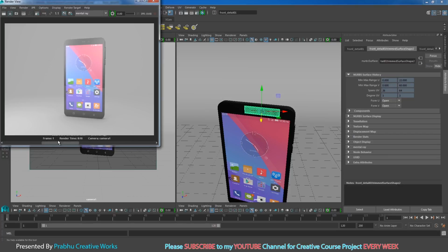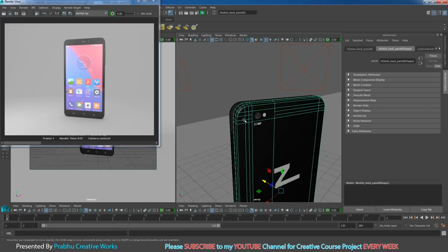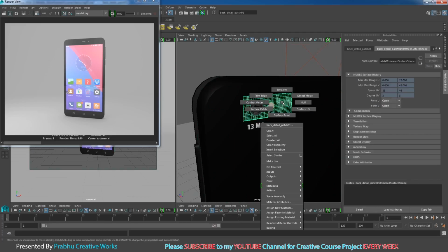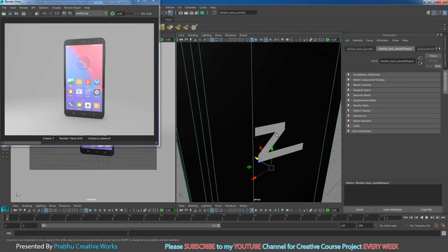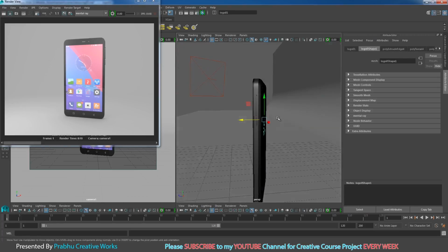You want to do the same thing on the back side. I will select the back panel, right click and choose material attributes. I want to reduce my specular color over here. Then select this one also, right click and choose material attributes. You want to reduce the specular color like this. Before that, see here, I forgot this Z logo. So I will select my Z logo over here.